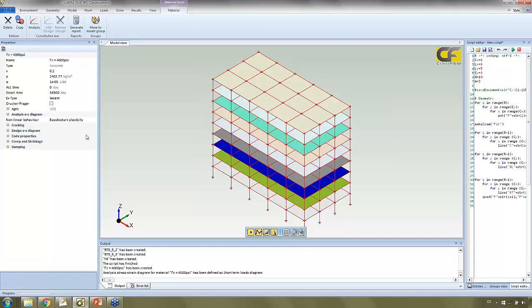Press OK. Well, now we are going to use the parabolic law, and we have different ways to solve it with the parabolic law. The Drucker-Prager plasticity, that is a special model for concrete behavior. Also multilinear elastic, if we are solving in an elastic way but parabolic, or multilinear isotropic hardening. I'm going to use this one for the nonlinear analysis. And we can also add cracking behavior. Here, clicking here we add the cracking properties we will see later in the nonlinear analysis.